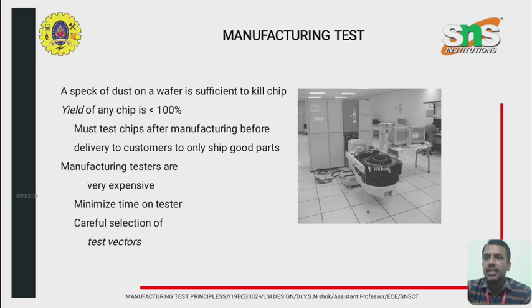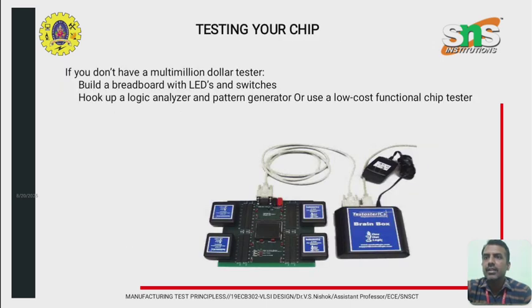And the testers are also very costly. If it is costly, we need to find another alternative method to test the ICs. That is given here. Build a breadboard with LEDs and switches and use a logic analyzer or pattern generator, which costs less compared to the testers.